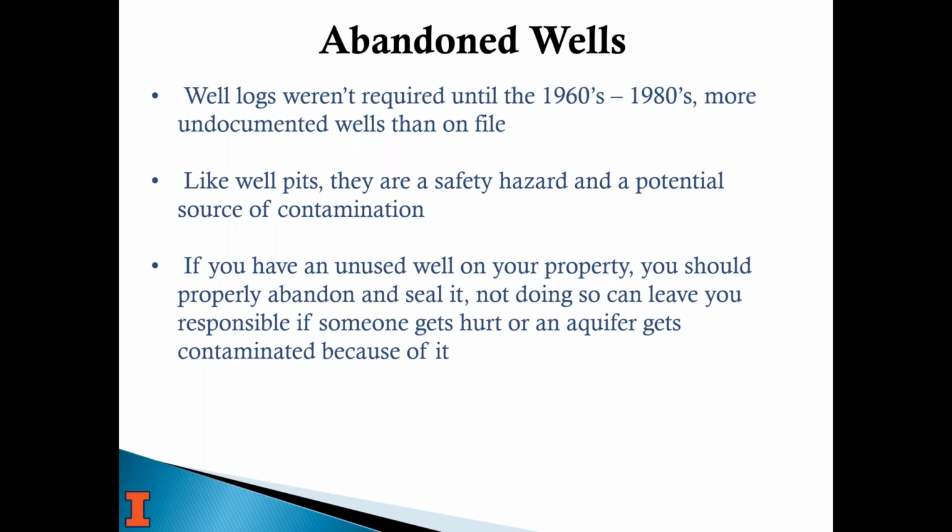And if you have one, whether someone's on your property and they're not supposed to be or not, if somebody falls in that thing and it kills them or hurts them, you're going to get sued. Or we've also run into cases where people just start throwing their junk down these old large diameter wells, old cans, even pesticide cans, things like that. If that ends up contaminating an aquifer and the family down gradient from you gets sick because of it, and they find that in their well, you're going to be liable. And so the best thing to do is to seal it and fill it in with clay grout or cement.